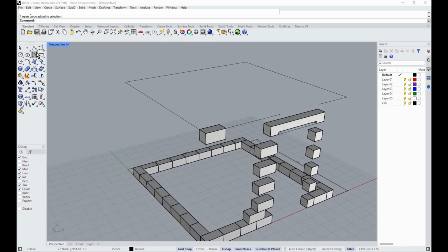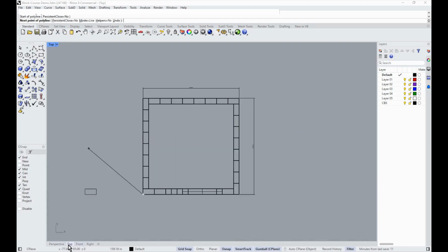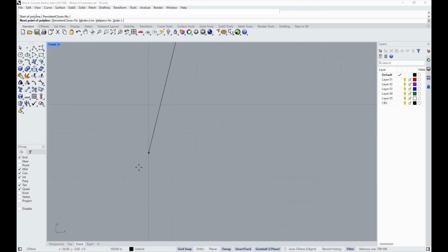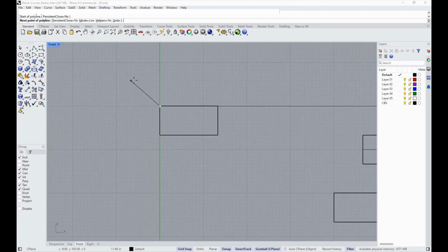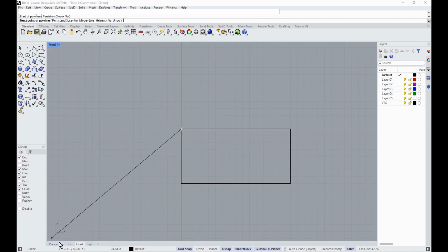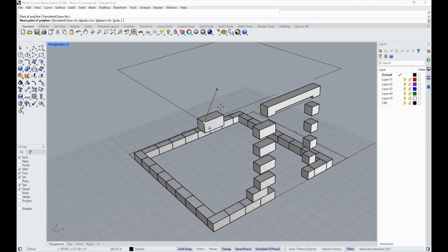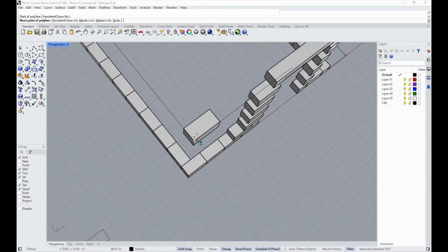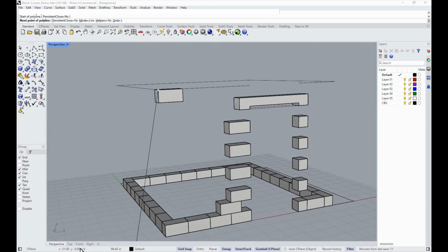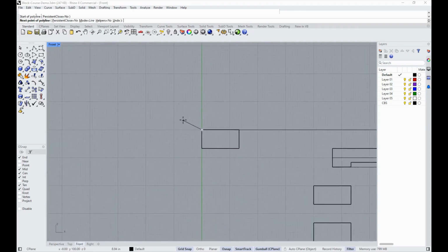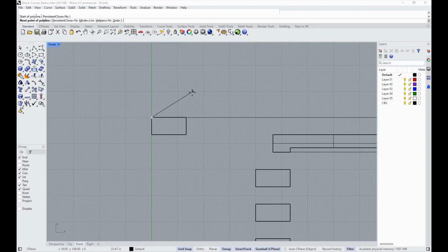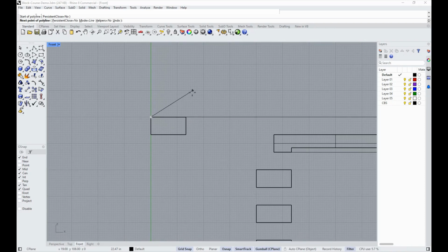And on here, we're going to start drawing a, let's do a 3/12 pitch. We'll start from the corner here and then get into a view that shows us that door. There we go. So one trick, so that's the front view. If you look, this thing is hovering right on X and Y equals 0, and then Z is at 96 up. So going back to it, as we draw things on here, it's going to stay planar to the surface using the normal commands. So Rhino and the sketch commands kind of work in 3-dimensional space, so something to keep in mind.